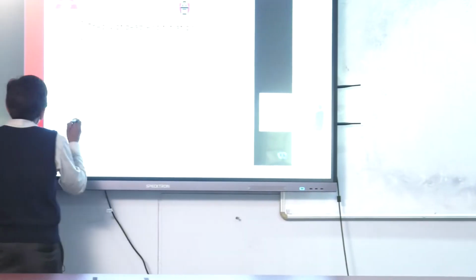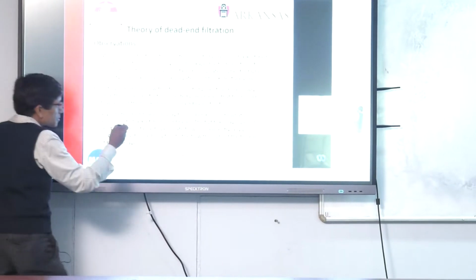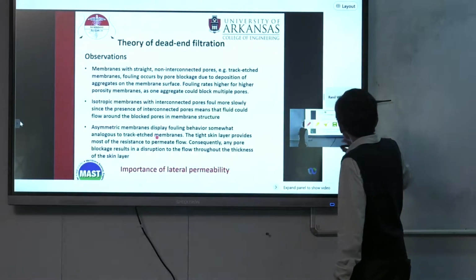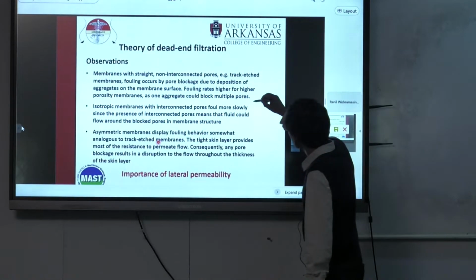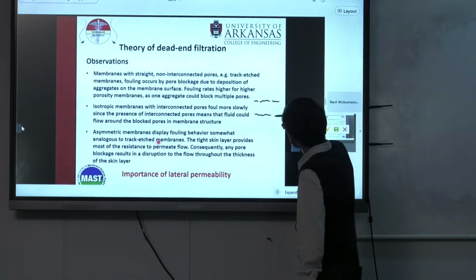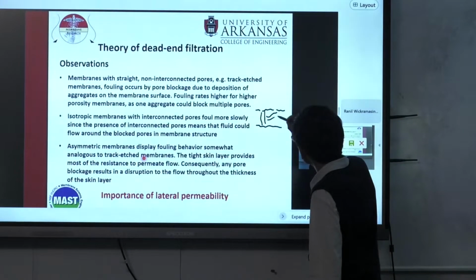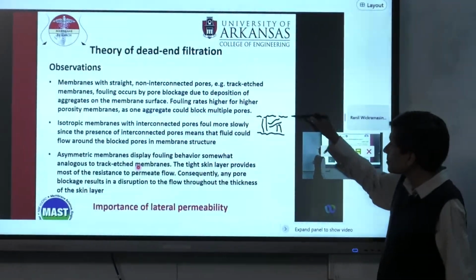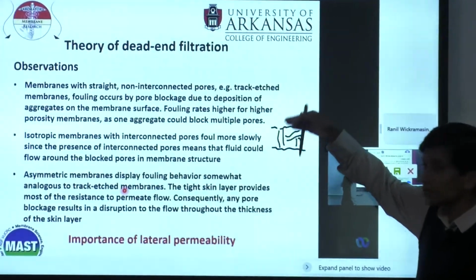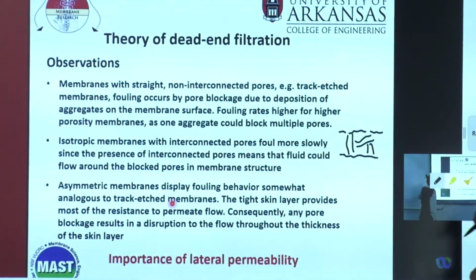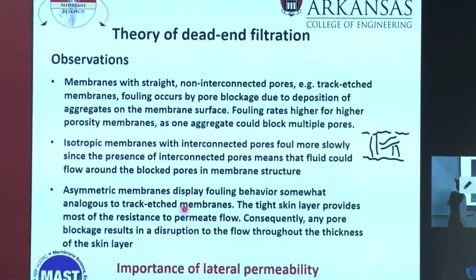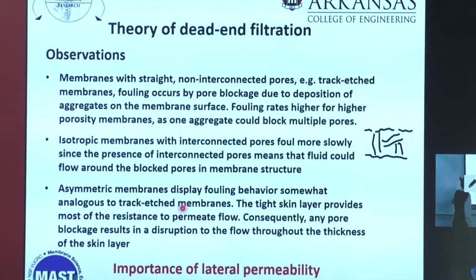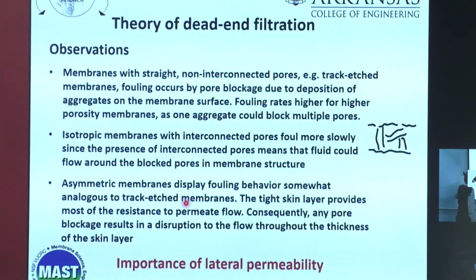If you think of a membrane, so you want your membrane to basically, here's your membrane, like this, and it's got pores like this, and it's got lateral pores and all sorts of things like that. Now, you want this membrane to have a certain pore size, so you have rejection properties. You also want to minimize the resistance to flow. So if you have a very small pore size, take a nanofiltration membrane because you work in water treatment, or reverse osmosis, you want very tight separation.